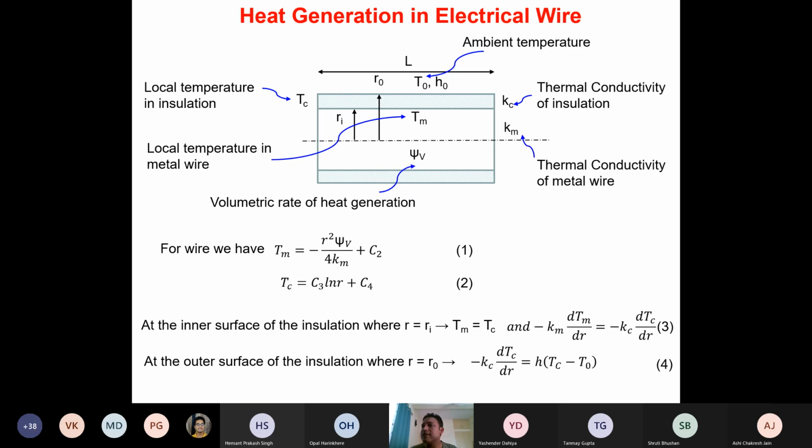In the last analysis, when we looked at the conduction chapter, the concept of convection we had not looked at till that point, and therefore we assumed the temperature here at the surface as T naught. But that analysis is not completely correct, because outside the surface there will be a convection taking place. So the additional factor of convection is present outside this, isn't it?